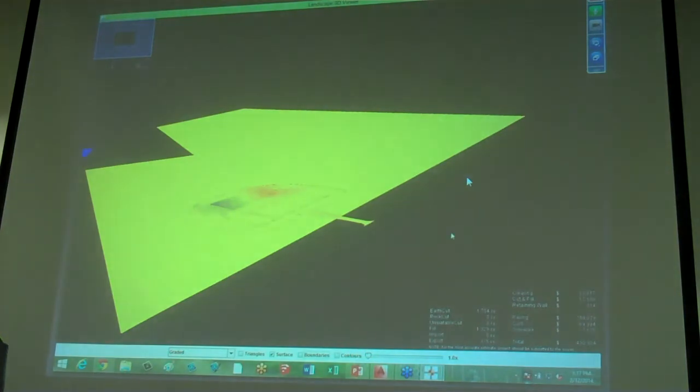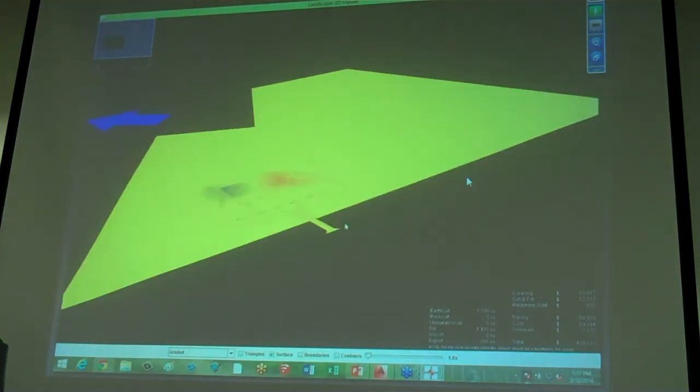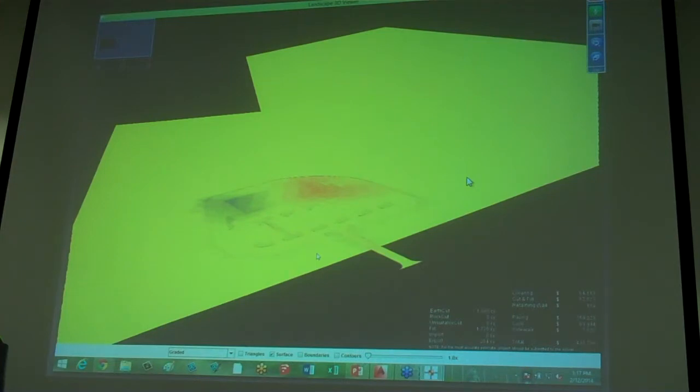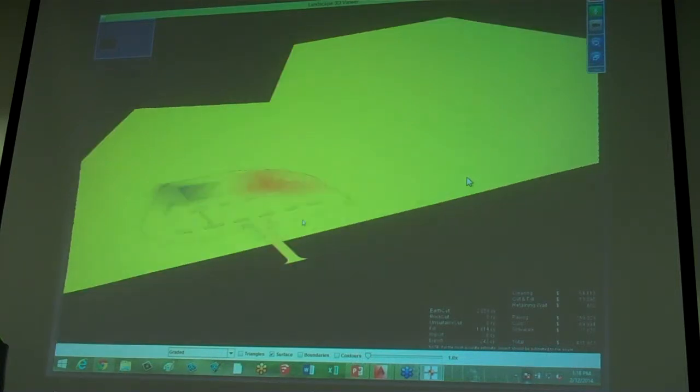And there we go. The biggest thing you look at first is not the image. I want you to look in the lower right-hand corner. I'm not doing one grading plan or two. SITEOPS is running through a couple thousand. It's looking at what is the best way, based on my slopes, my material thickness, all my constraints, to grade this site? And I can see that red is cut, blue is filled, yellow means very little to no elevation change. It's only grading what it has to do.